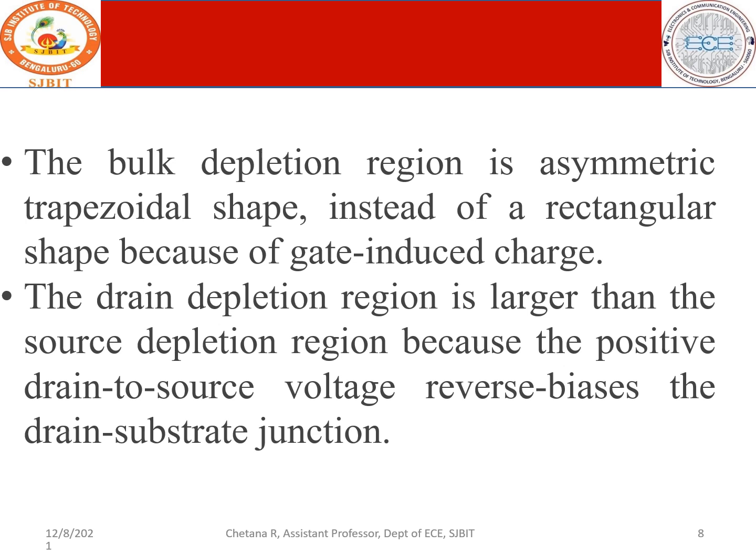You remember VDS less than VGS minus VT is where the potential is applied at the drain, and that is how we get the linear region. In case we apply the voltage such that VGS is greater than VDS, which is greater than VGS minus VT, then it is the saturation region. So everything happens at the drain junction. Therefore, the drain depletion region is larger than that which is occurring at the source.